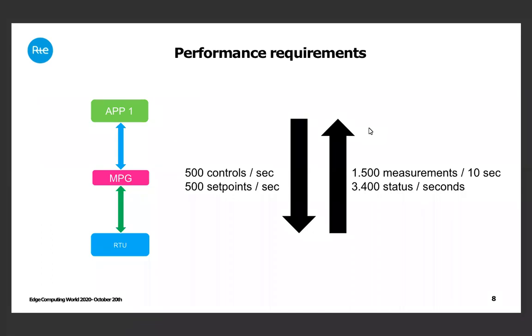Yes, the information that we are gathering from the field, and the controls, are pretty simple actually. The measurements we have, for each line and node in the grid, are the voltage and the current, and we translate that into power, active and reactive power, and we need also to have the state of the switches and of the substations and to be able to control them.